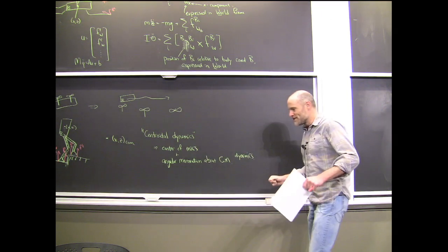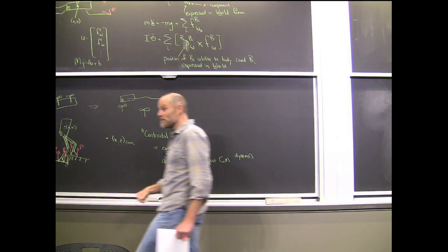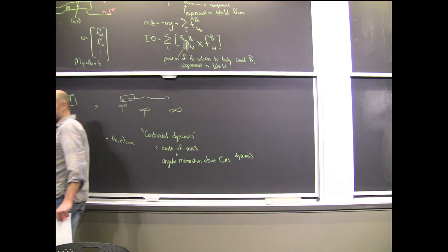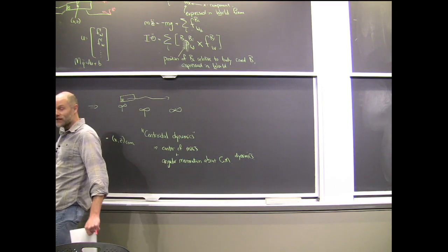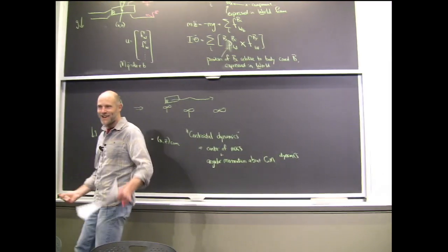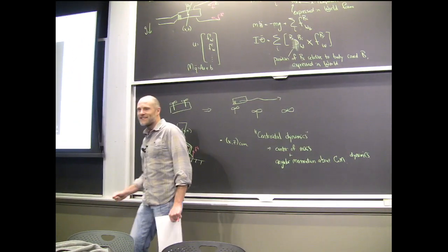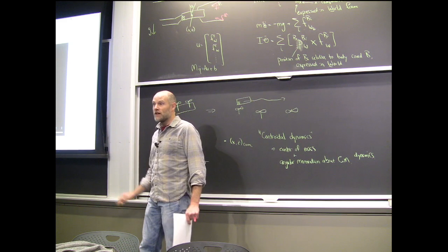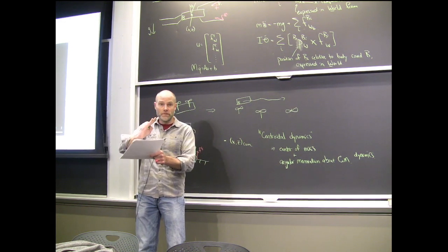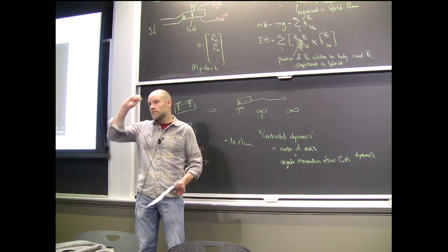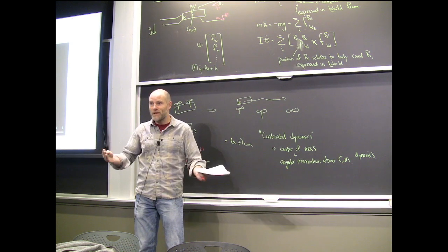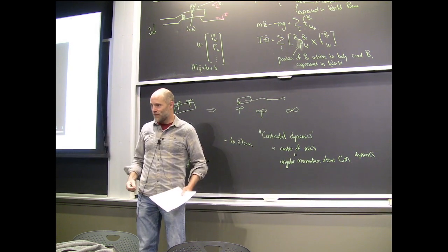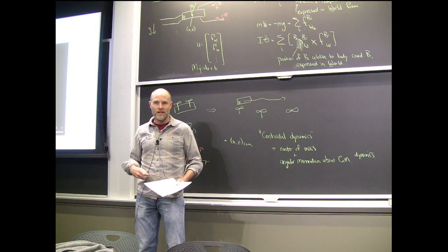So one of the reasons you see this, and then you can simplify it, just ignore collisions, is that effectively you're setting your foot down softly enough that there's effectively no collision. So the picture of this hybrid jump kind of disappears. Okay, you lose something because impacts are good. They were stabilizing in the rimless wheel and in general are a stabilizing phenomenon.